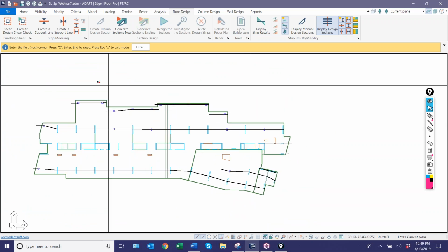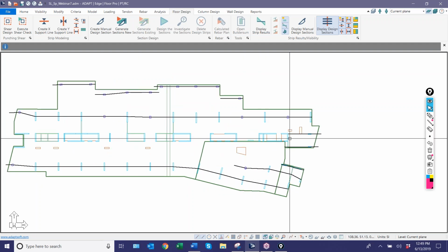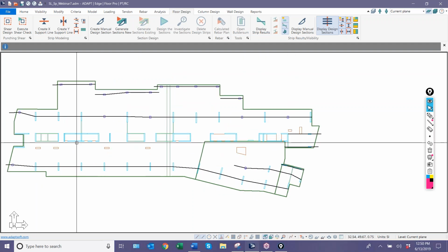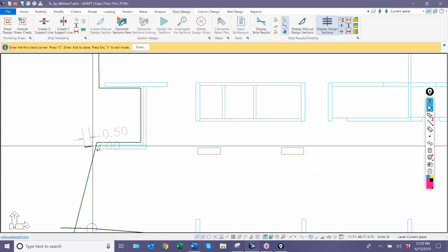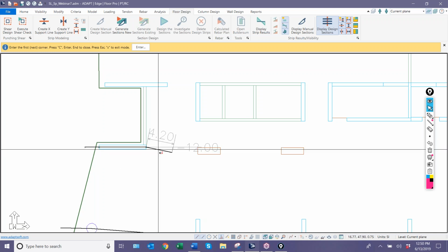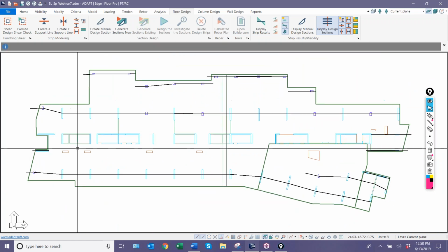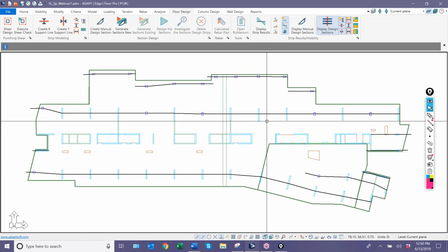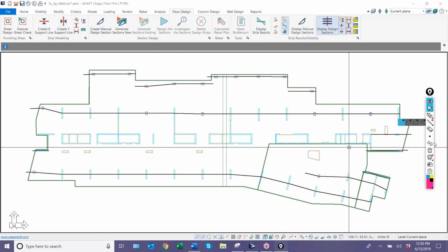So now we have our setup for the X direction. Okay, now again I want to avoid any strips in this core area. So let me add one more for this wall down below. So what I'm going to do first is I'm going to bound the edges off with splitters. I'll add a splitter that starts here. Remember this point is inside the slab edge, so I'll just run that up vertically and run it down to the support line.